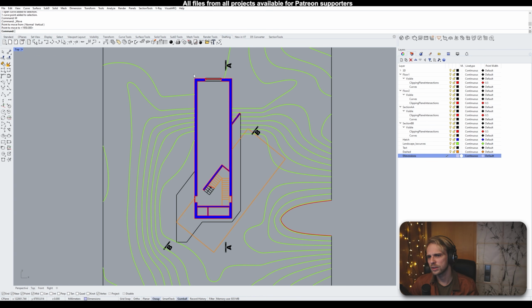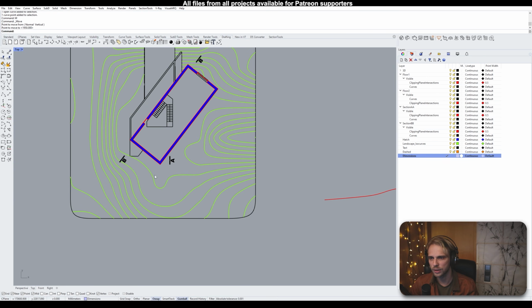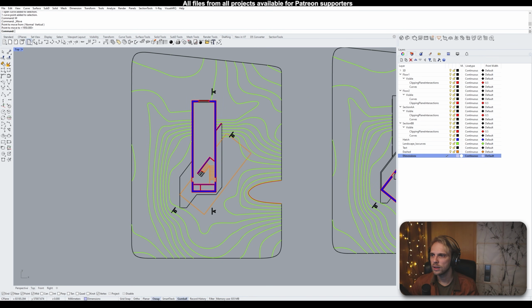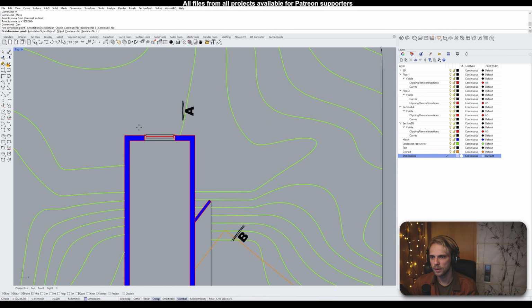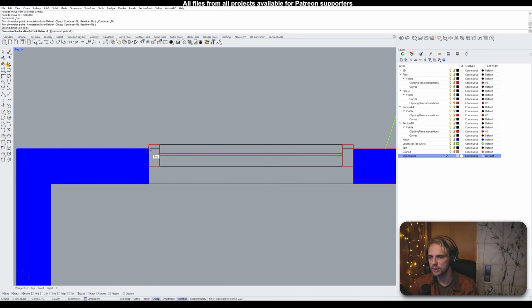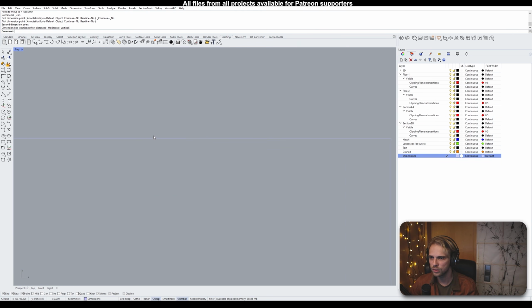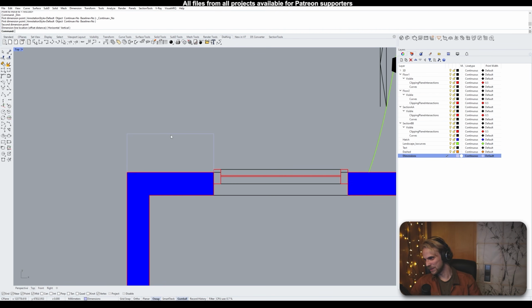The linear dimension for stuff that is aligned with XY angles, and aligned dimension for something that is a little bit more crooked, a little bit funky. So if I were to just create a linear dimension right now, it creates exactly how you would envision it creating in AutoCAD. Click once, click twice, and drag out that dimension. And if I zoom in hard enough, I'll see the number. But it's pretty small.